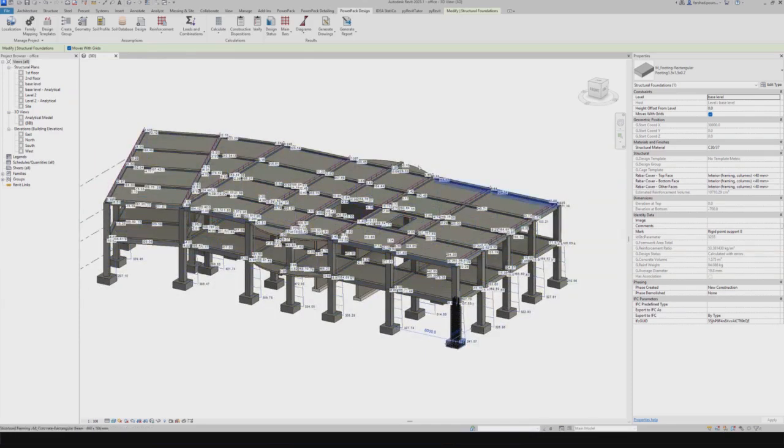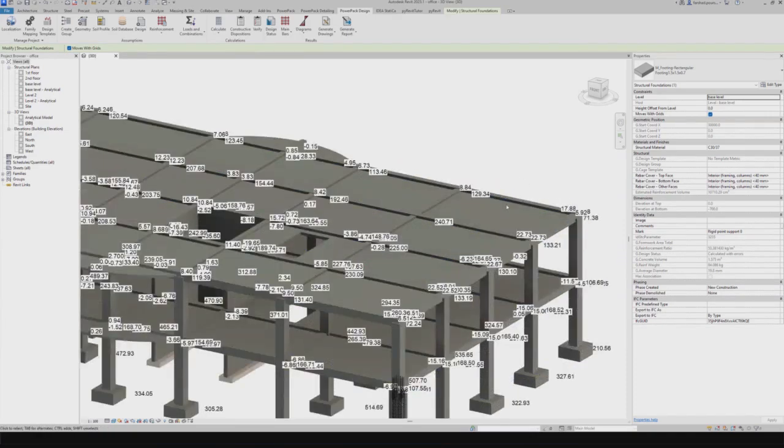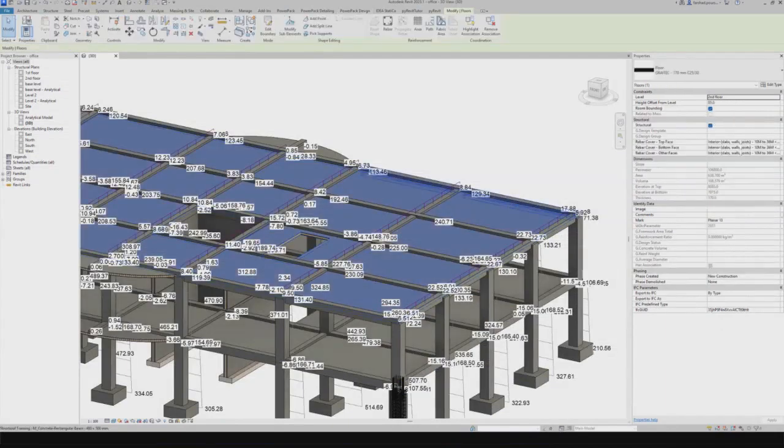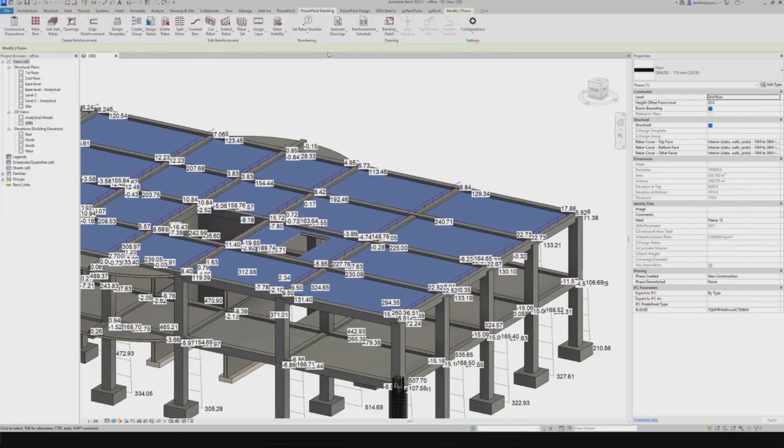If you remember, we also brought in our rebar area from Advanced Design, which we can use in that calculation to apply our rebars to our slabs. So in this case, I can use our Power Packs again. You just select the slab, go to Power Pack Detailing, and here I have the slab tool. I will click on Edit Window.